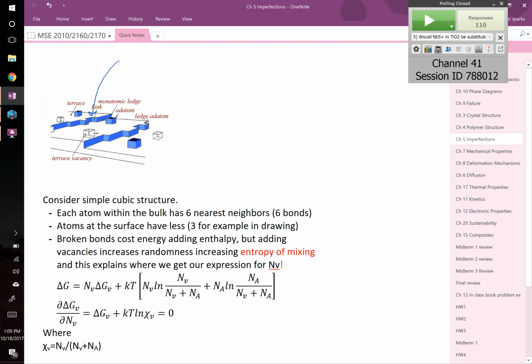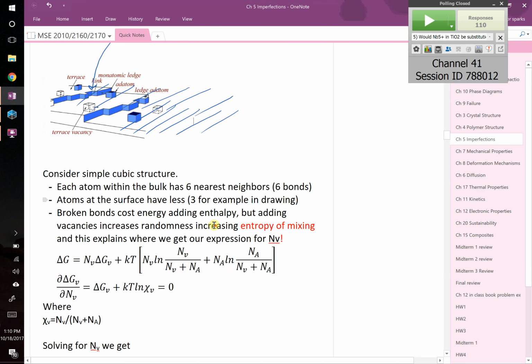So because of this, when you grow crystals, and you're either introducing new atoms or you're pulling atoms out of the center by creating vacancies, they will go to specific spots. And you can actually see this. They've taken really clever videos of this happening where they can see that they grow along these edges, right? This edge will keep on growing along there. And then when that's done, it'll start a new one. And then that one will grow along that edge. So they grow in specific ways, and they do so to try and maximize the number of bonds that they can form along the surface. Okay? We can use this though, right?